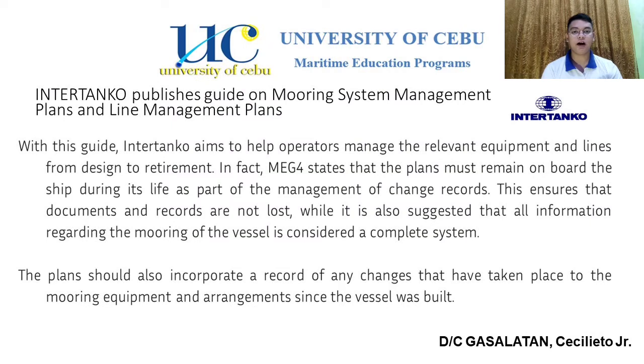Intertanko publishes a guide on mooring system management plans and line management plans. With this guide, Intertanko aims to help operators manage the relevant equipment and lines from design to retirement. In fact, the MEG 4 states that the plans must remain on board the ship during its life as a part of the management of change records.